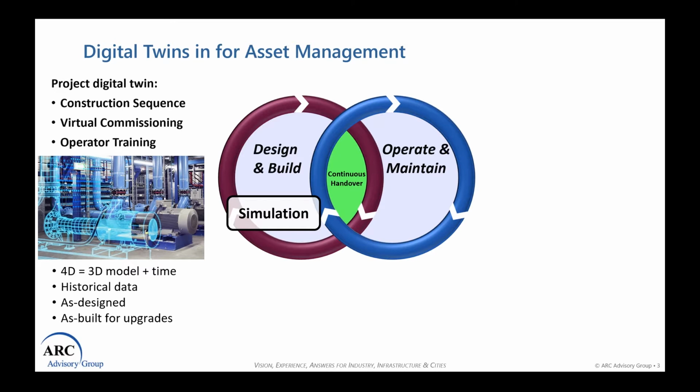And there's a couple, the construction sequence. So, you know, you have that object. Do you build the outside of the building first and then put the piece of equipment in there? Or is the equipment so large? This is a simple example. Is the equipment so large that it doesn't fit through the door? So you've got to really not build the door or not build part of that wall until you get the piece of equipment in.